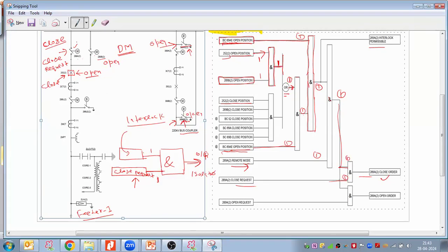On-load switching, yes, right? By the way, the isolator is also switching. Let us assume that earlier, from the double main bus bar, we closed one of these isolators, but now we want to switch these isolators. In order to close these isolators, the criteria we have to satisfy is that this breaker should be in the closed position.